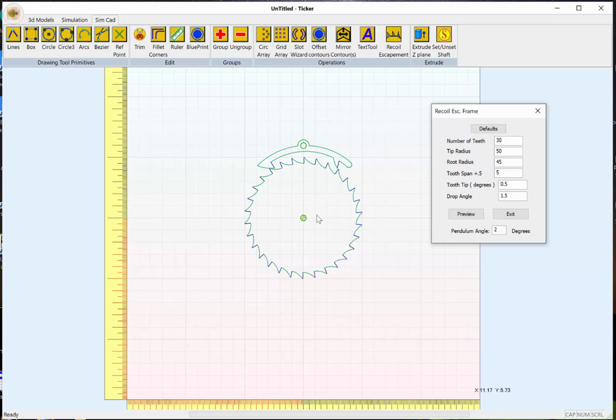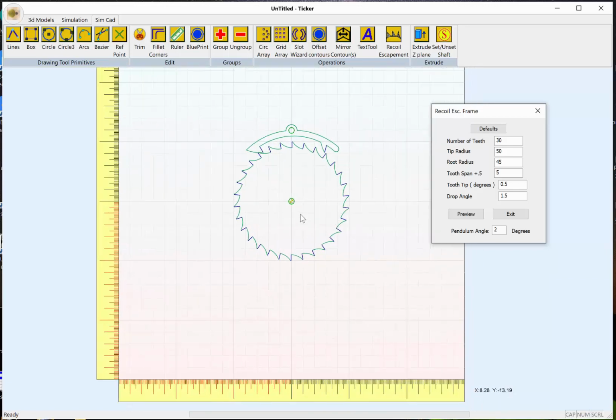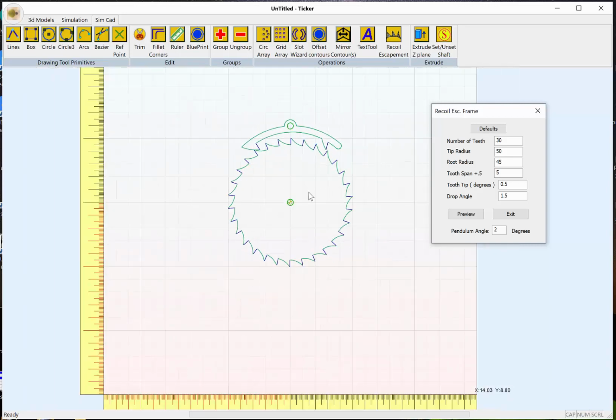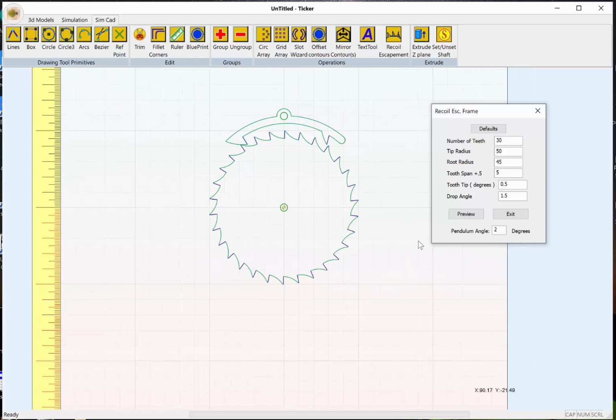And thus you would only need 10-to-1 and 10-to-1 again in two different ratios to get minutes hand and an hour hand functioning properly. So really, how many teeth you select at the beginning of an escapement such as this is determined really by the length of your pendulum and by whether or not you want to have a second hand on the clock.